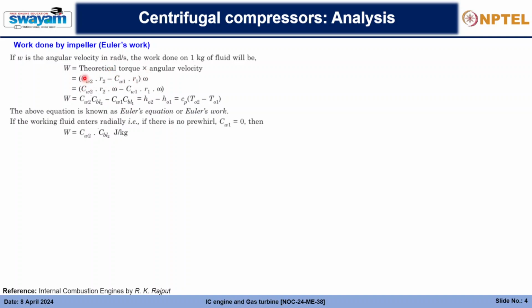So whirl velocity at the outlet times its radius, minus whirl velocity at the inlet times its radius. So the whirl velocity is finally contributing to the entire torque. That's why we subtract, and that will be the net torque. And finally, this is r times ω. The ω is the angular velocity, and it remains constant for the inlet and the outlet. So r2ω minus r1ω: r2ω is the blade velocity at the outlet, and r1ω is the blade velocity at the inlet.